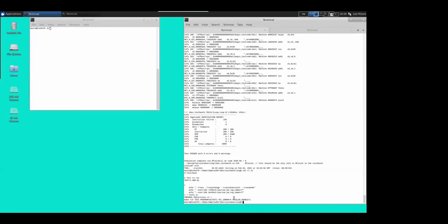And then on top of this, we have a set of comparison checks which tell us whenever there's a difference between the RTL and the Imperas DV environment. And when we have those, we have the capabilities of being able to perform additional tracing and interactive interrogation to see why those differences occur. So we can quite quickly narrow down the problems and determine the correct resolution to why we're getting incorrect or non-intended behavior in terms of the RTL versus the reference.